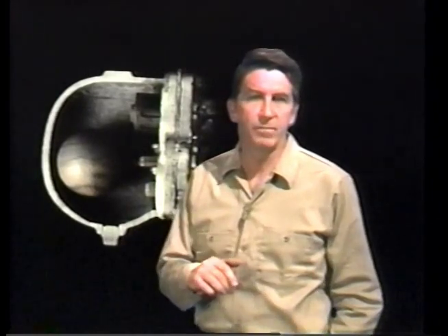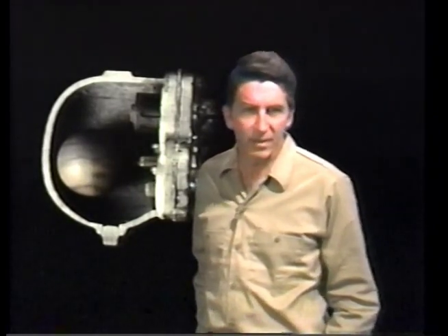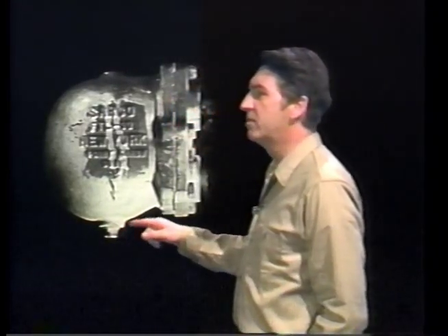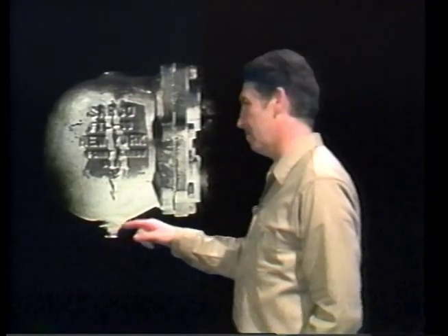And finally, since float traps never empty completely, they can freeze. But keep in mind that steam traps that are in operation rarely freeze. The warm condensate flowing through them usually prevents freezing. See, the real danger occurs when the trap system is shut down and the condensate cools. So, if you shut down a trap system that has float traps, be sure to drain all the water out of the casing. Now, most float traps are equipped with a drain plug for just this reason.